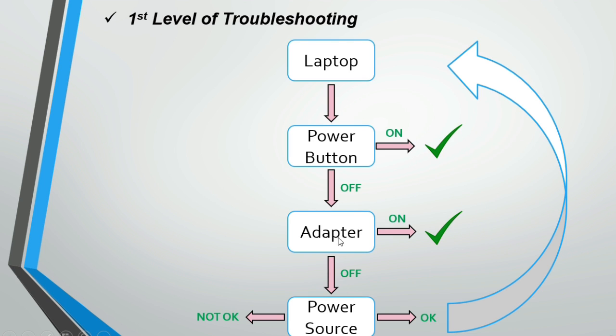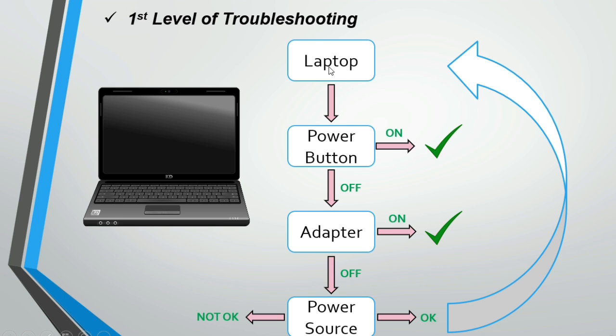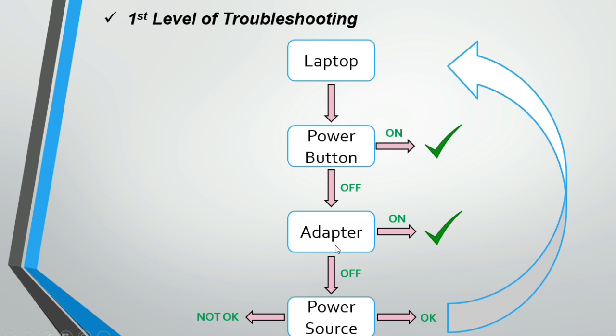If we replace the 19-volt adapter and the laptop turns on, that means the problem is in the adapter. If we replace the 19-volt adapter and the problem persists, the laptop is still off, so the problem is not in the adapter. We should check the power source.